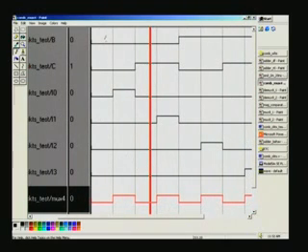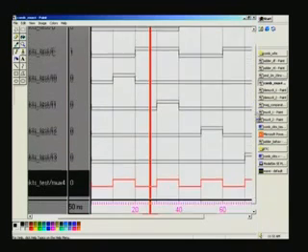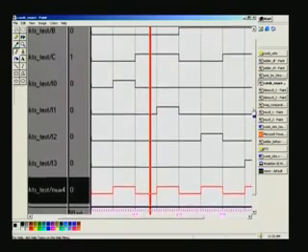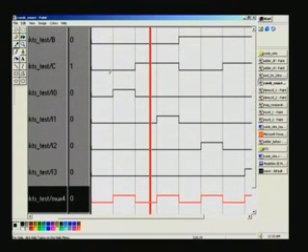It's once again in binary progression, 0, 0 here up to this. This is 20 nanoseconds. All waveforms are marked by 20, 40, 60. And so here it is 0, 0, then 0, 1, 1, 0, 1, 1. So only 4 combinations are there because BC are only 2 bits, right? 2 bits means 2 to the power of 2, so 4 combinations only are there.